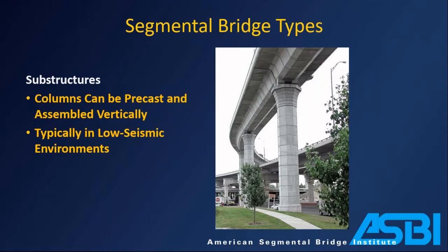The last thing for the precast options is precast substructures. I guess if we really wanted to, we could claim that regular cast in place columns that are done in lifts are cast in place segmental. Nobody's really tried to take ownership of that yet, but you can also do precast substructures. It's a very efficient, very quick way to put things together. The segments are cast just like the superstructure. They're post-tensioned together, usually a combination of bars and tendons, and post-tensioned into a cast-in-place foundation.